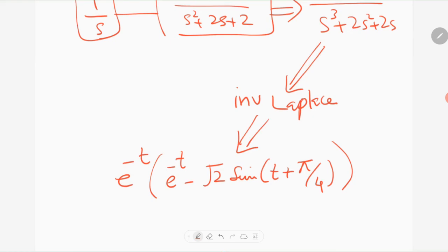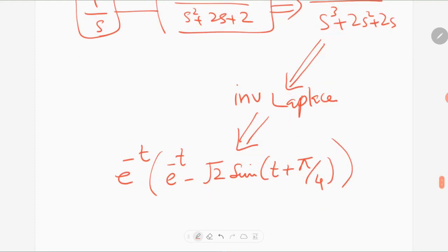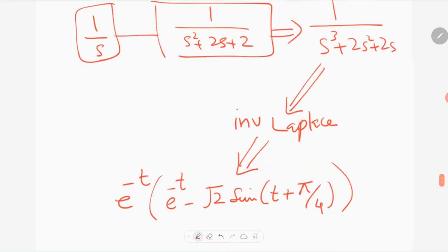So just by adding this s, we can see that our Laplace transform has changed drastically. So I'll take this opportunity to mention this advantage of the Laplace transform, that when this signal is represented in the Laplace transform, it is simply the multiplication like this, right?